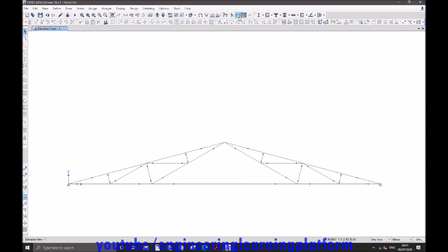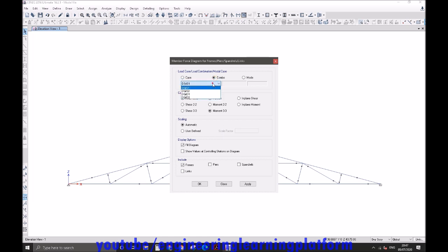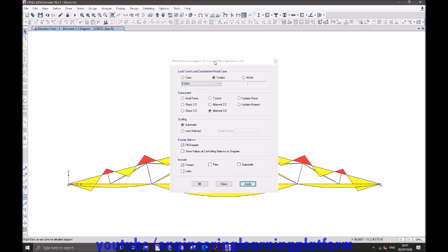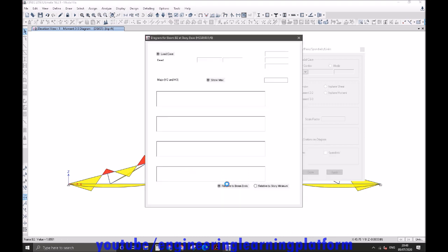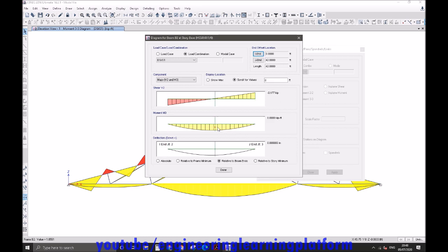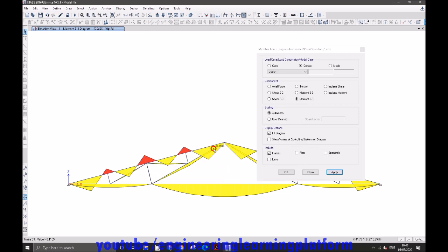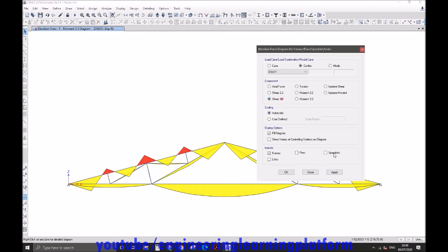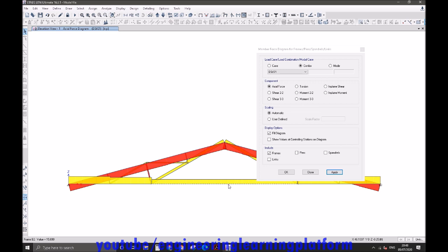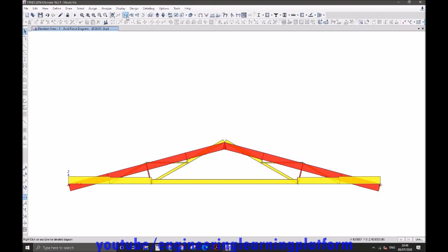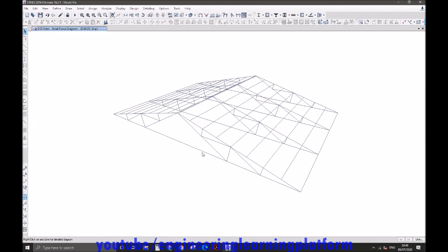Okay, so now we'll proceed to the design part. Let's check the moment diagrams just to show you that the trusses have very negligible moment, which is usually, or most of the time, due to the self weight only. As you can see, the value of the maximum moment is only 1.8 kip-ft. You might have come across in your experience the number of kip-ft a flexural beam can take. That is 200-300 kip-ft moment for a small size beam, while the moment we are getting and the shear force is very low, which is reasonably due to its self weight.